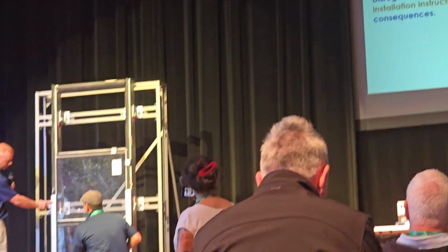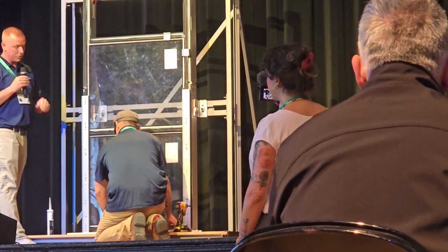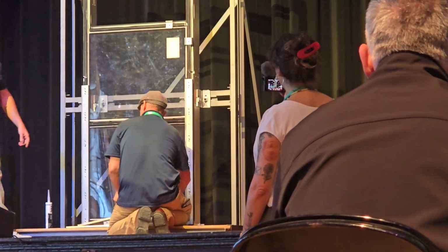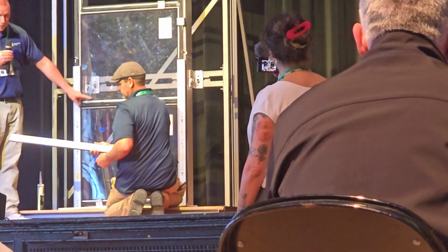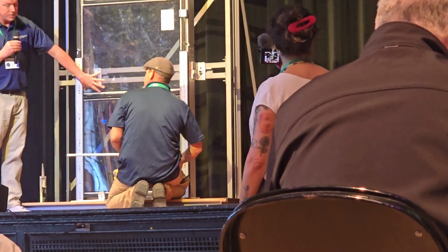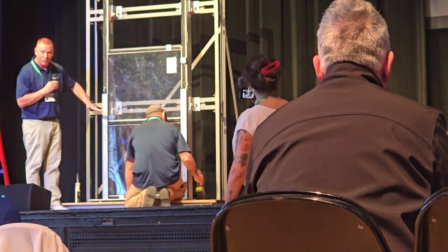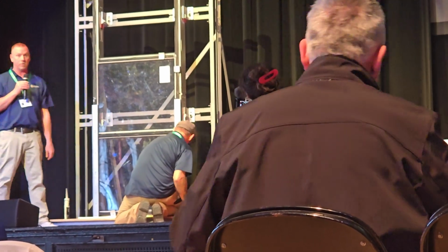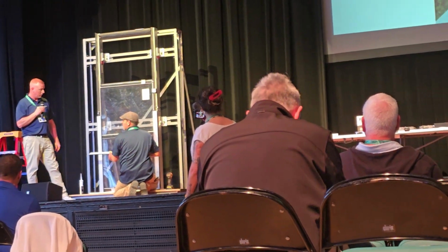For the verticals, there are all these extra holes in it. These will all be sealed before we put our covers on. And for the horizontals that Bill's installing right now, you'll notice that there are slotted holes, and we're going to face them up. And that's our weeping system. So when water finds its way inside somehow, it's able to go through that channel, through that zone, and funnel down with that ramped ceiling, down underneath the setting blocks, and that could escape the curtain wall from the bottom of the beauty covers and through the pressure plates.